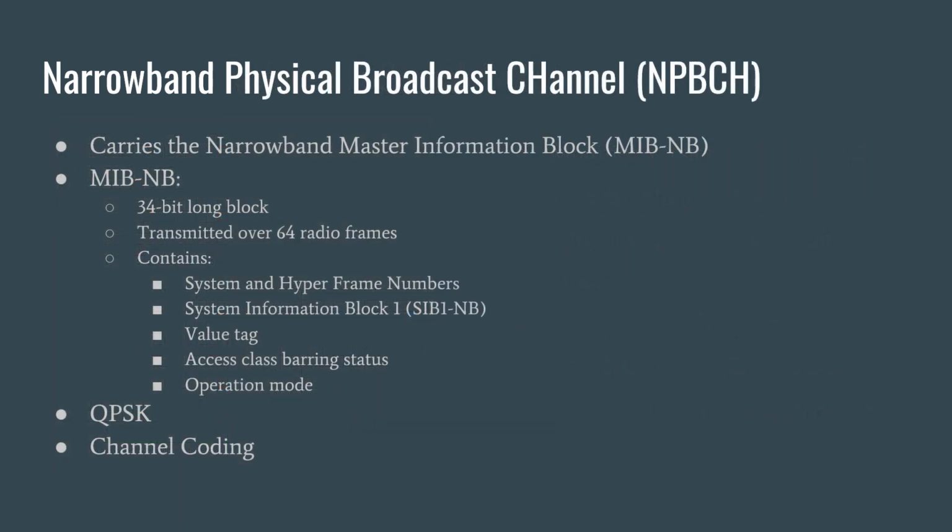The Narrowband Physical Broadcast Channel, or NPBCH, is used exclusively to carry the Narrowband Master Information Block, or MIB-NB. This is a 34-bit long block that is transmitted over 64 radio frames, which takes approximately 640 milliseconds.